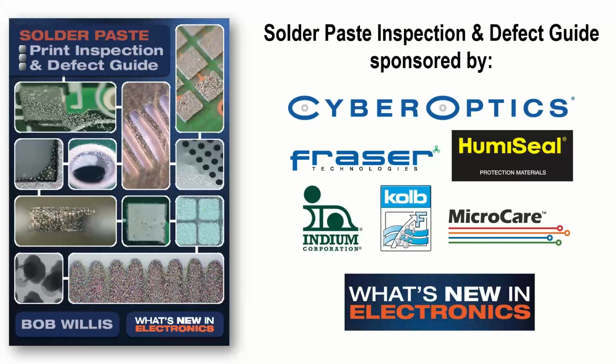If the quality of the printing is starting to deteriorate, you shouldn't be using it. So it's all about checking the quality. So it's checking the quality of the parts you're using in your process, just the same as any other material. And to do that, it's ideal if you've got SPI, because all that information is being generated for you every time you produce a board.